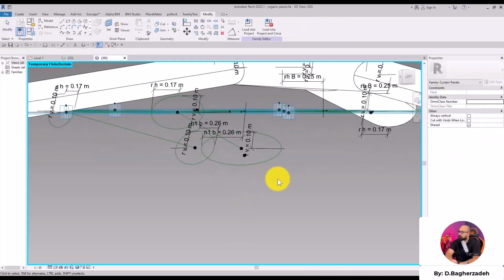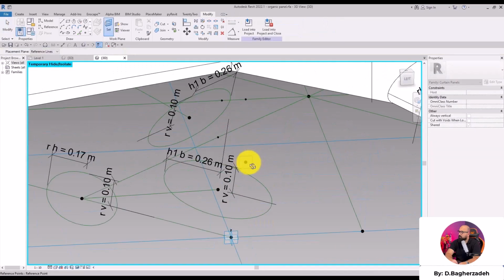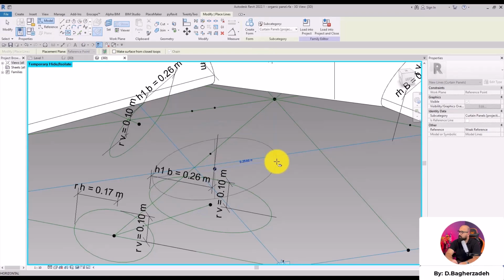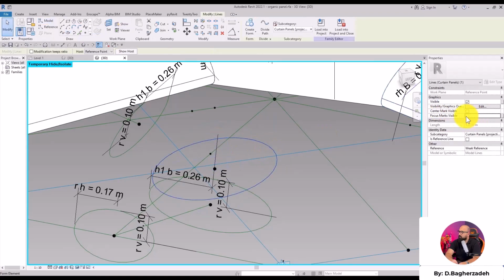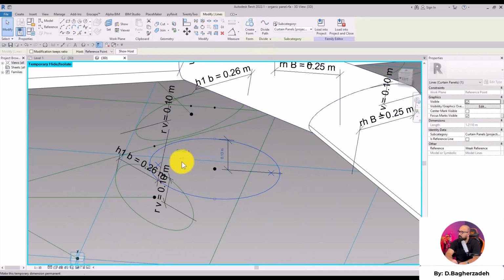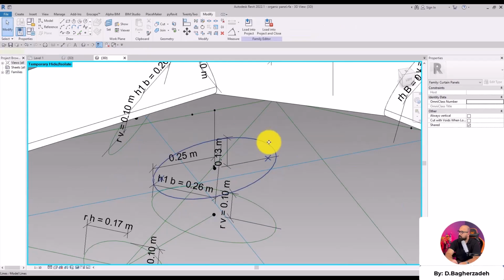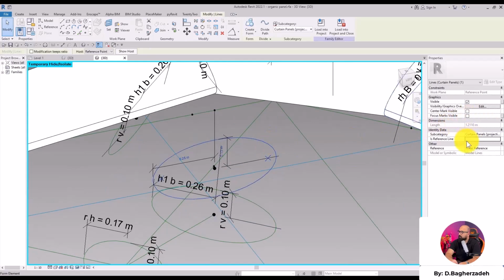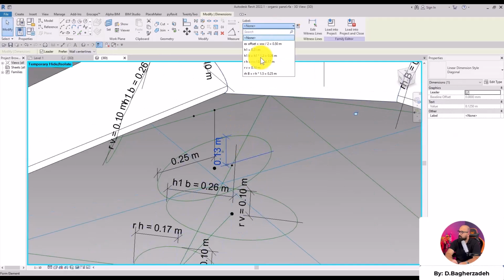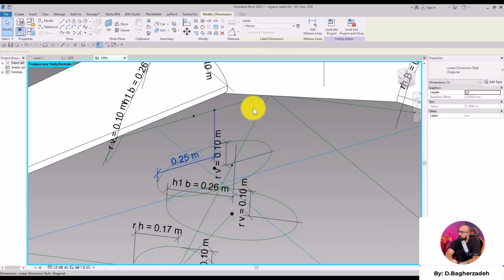Now enter the proper view, which is this one, and set its work plane. And then try sketching another ellipse. Afterwards, make it a reference. Then set its dimensions. Exactly like before. What happened? Oh, I just clicked on focus visible instead of reference. Now, select the vertical dimension, set the RV parameter for it. And then for the larger one, exactly like before, we need to go with RHB.